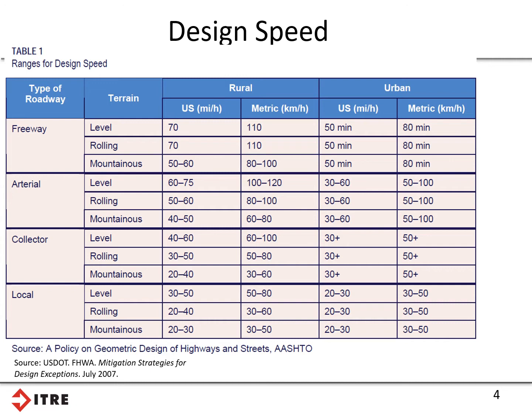So if you look at the design of horizontal curves and vertical curves, they are highly impacted by the design speed that is selected. The actual characteristics of those curves are highly influenced by the design speed. Design speeds can change throughout different segments of a project, but the focus, particularly in recent years, has been to gain some consistency along roadways, in that the more consistent we can keep a design speed throughout a roadway, generally the more predictable and therefore the safer it will be for a driver. So keeping design speeds within some level of consistency is useful and important.